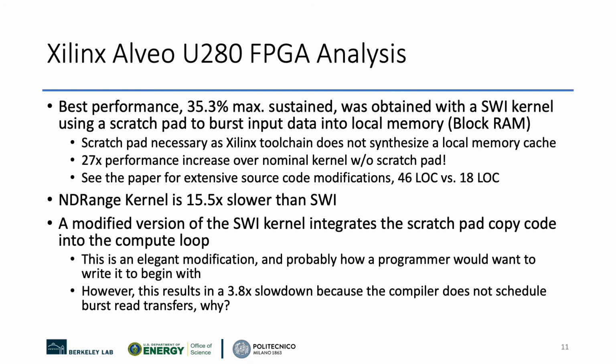With the scratchpad logic, the compiler is able to schedule 512-bit burst transfers. Without the scratchpad, it only schedules 64-bit transfers. This and more effective burst transfers enable more effective use of the HBM interface.